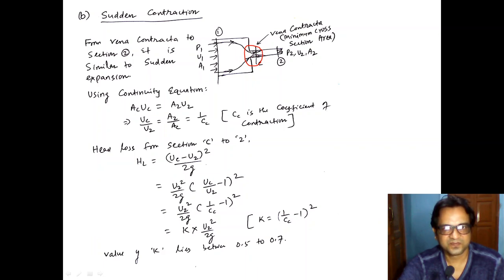So this area is the minimum area available for flow. Also, you know, with the stream function, we can find the volumetric flow rate between two streamlines as the difference of the two stream functions corresponding to those streamlines.